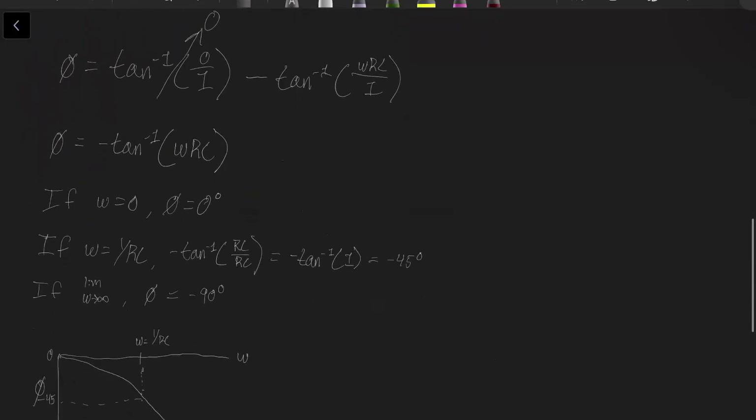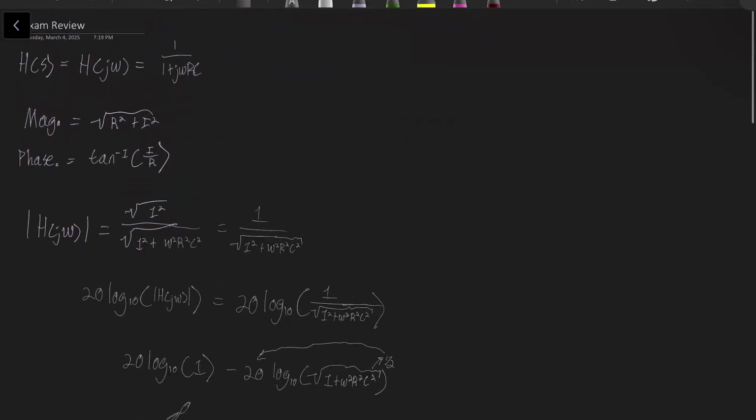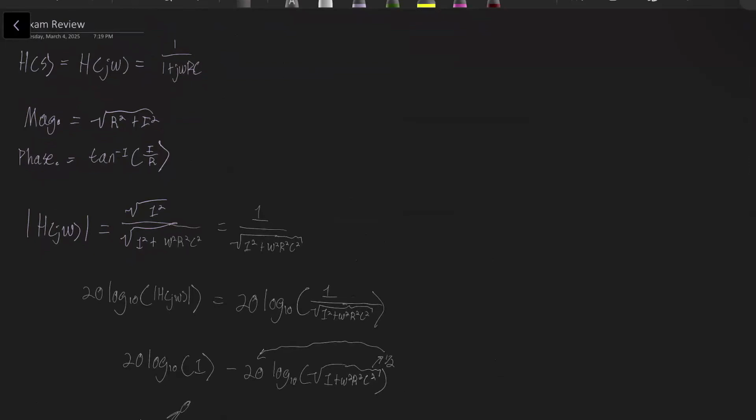Yes, DC gain. So you get DC gain by making your j omega or s values equal to 0 and taking whatever is left. So for example, in this equation, if you substitute your j omega with a 0, your DC gain is just going to be equal to 1, right?